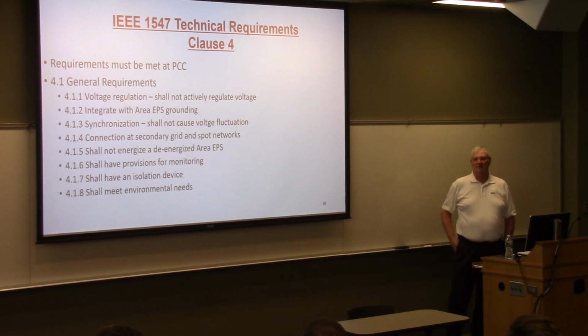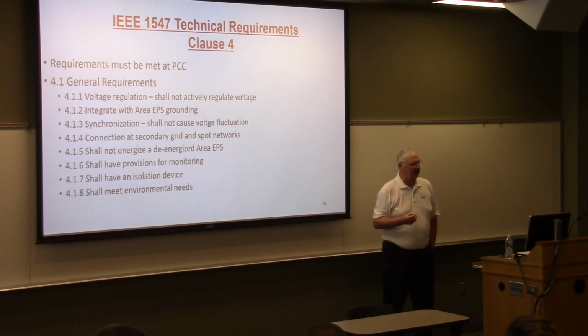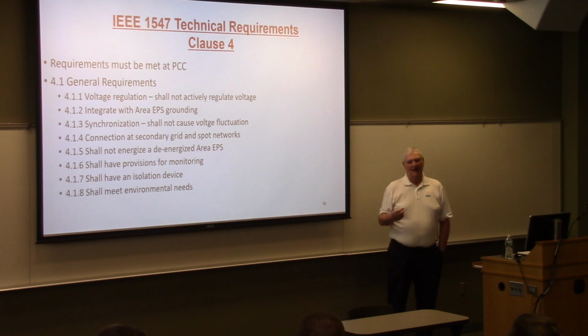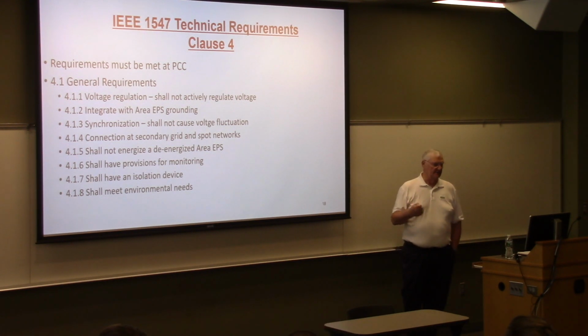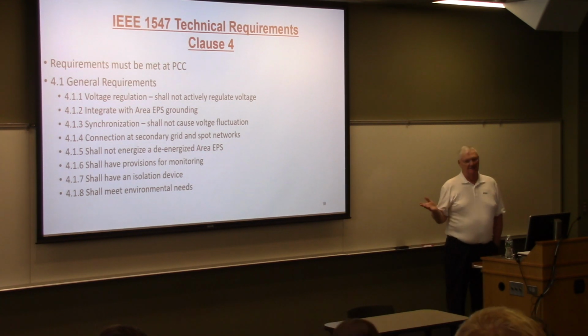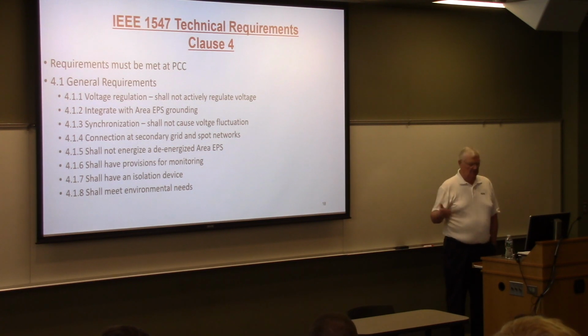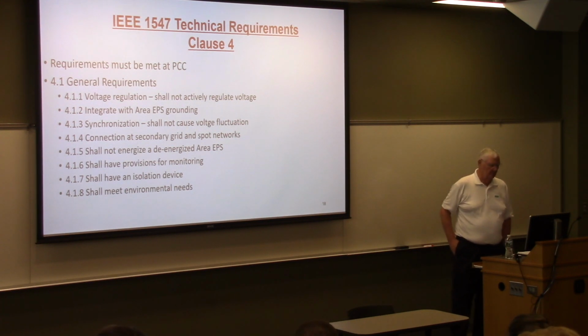It has to integrate with the grounding. A significant impact is how this system is grounded, where it is grounded, and what kind of detection do you have on it. Synchronization, if it's an inverter, it's usually not a big issue. If it's a synchronous generator, you have to synchronize, but it's a relatively simple thing to do.